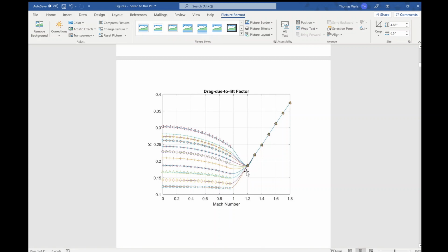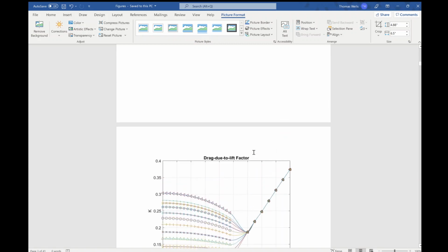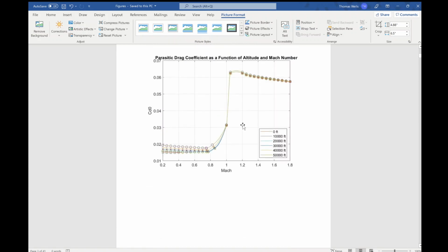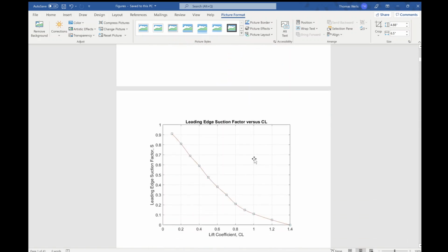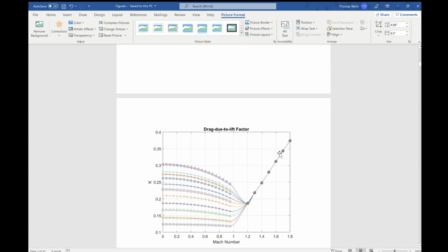And then once you reach the supersonic regime, they collapse as, I believe, 1 over CL alpha, or your lift curve slope. And then all the graphs collapse onto a singular value that continues to rise as this value up here continues to fall. Since this is the inverse of it, it will continue upwards as you increase in Mach number.